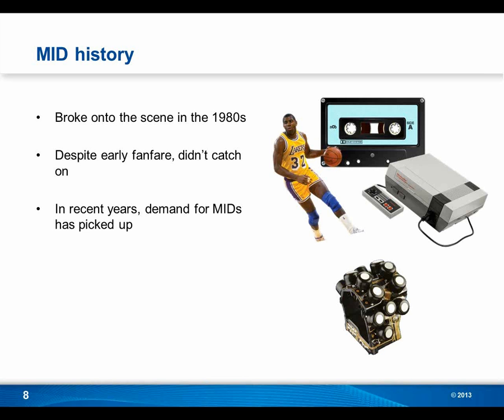Now, why was this? Well, the main reason was that the threshold for entry into the world of MIDs was really high. This was due to the high cost for tooling to create your parts for MIDs, and there's really no flexibility for mixed manufacturing environments or for prototyping. So basically you had high cost for tooling and a situation where only very large quantities could be manufactured.